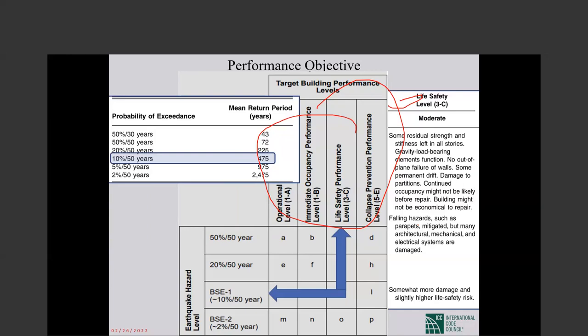Earthquake comes, applies to the building, and goes, finishes. And because of that, we accept damage. We say, just bear with the earthquake, just keep the integrity. The direction of the earthquake changes, okay, we live with it. But the gravity load is always there. So if damage in the gravity load resisting system happens, it's gone.